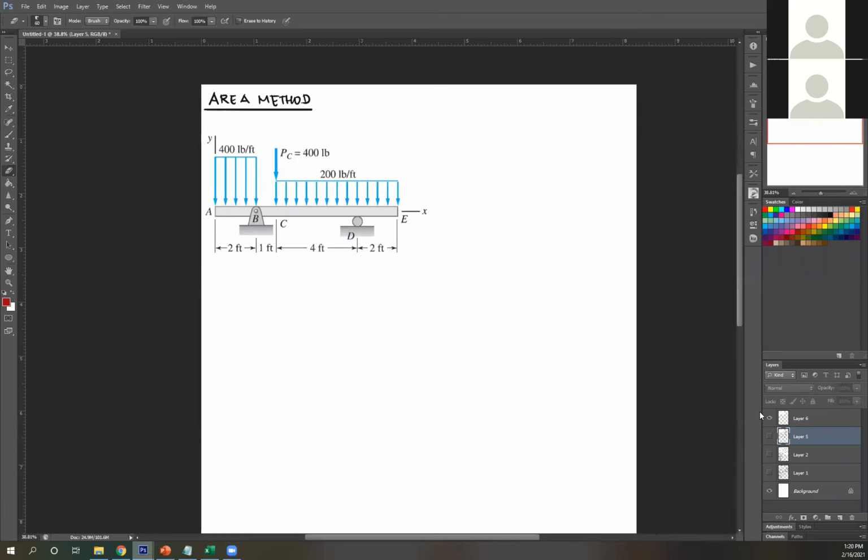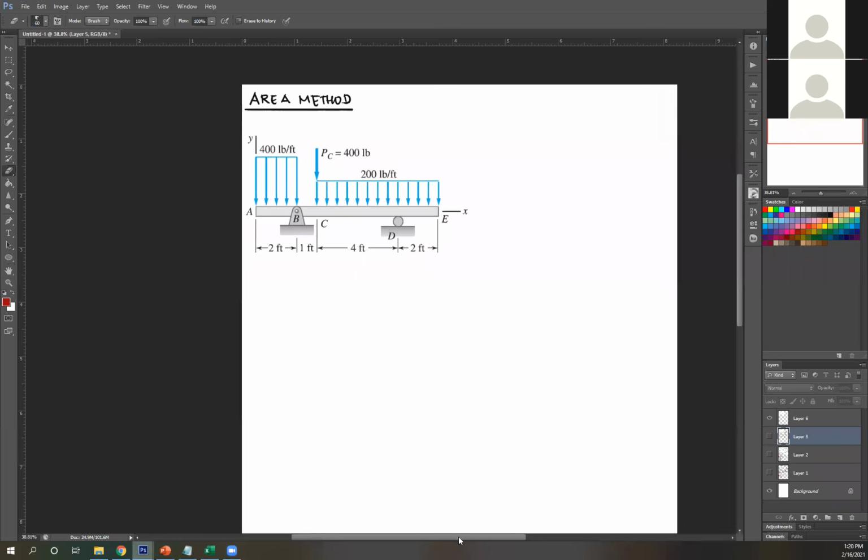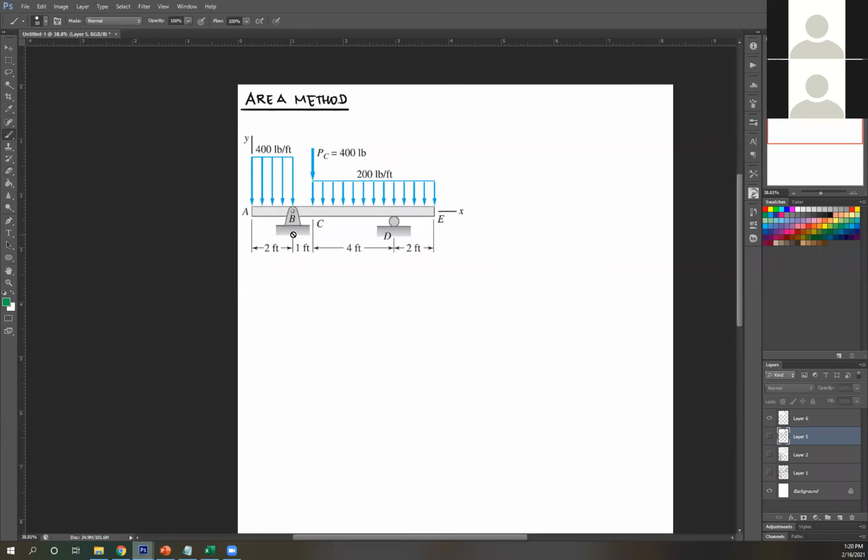Okay. So again, first step, find out your reactions. So let's call this RB, and let's call this RA. And remember, there's no horizontal force, so there's no horizontal reaction of your pin support. Okay, so I want to solve for reaction, so let's start with moment. So let's take moment at B. You can start with moment at B, you're going to get the same thing. If you want to practice, do that. So summation of moment at B equals 0.